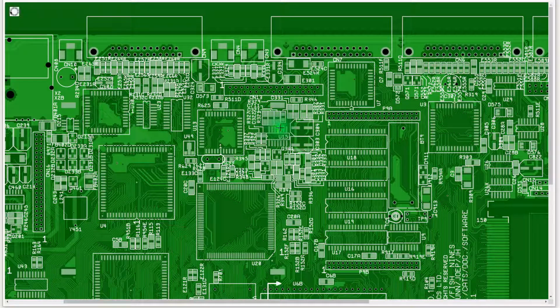I want to look at the various inputs and outputs on the op-amp chip over here. I want to look at the power rails on it. There's where the minus 12 connects. There's where the plus 12 connects. So having an idea where I'm probing helps.